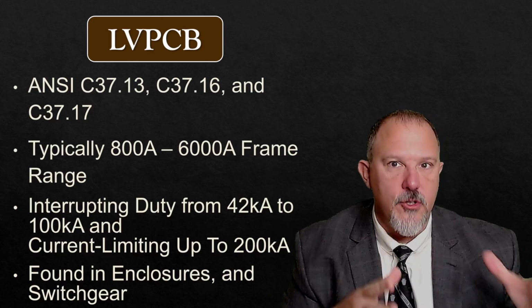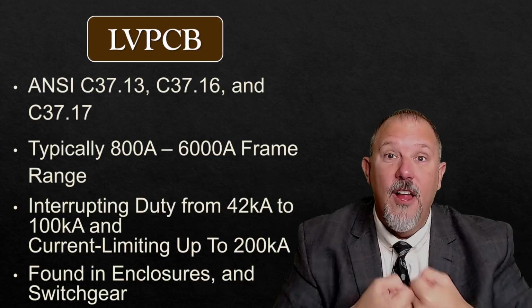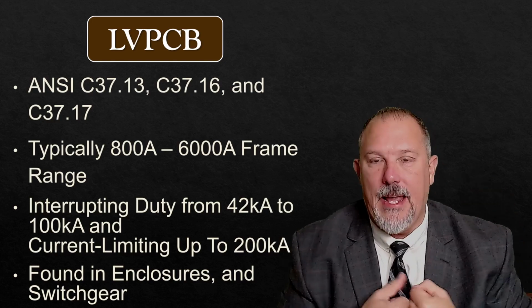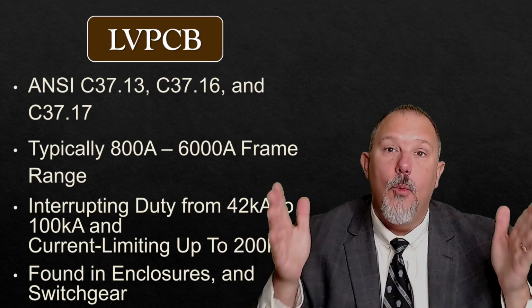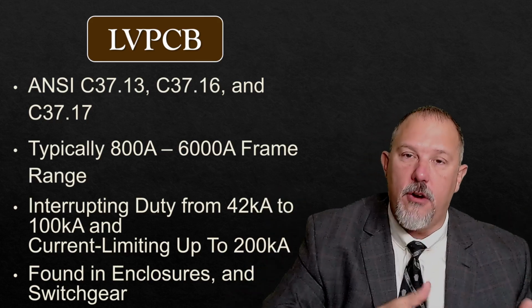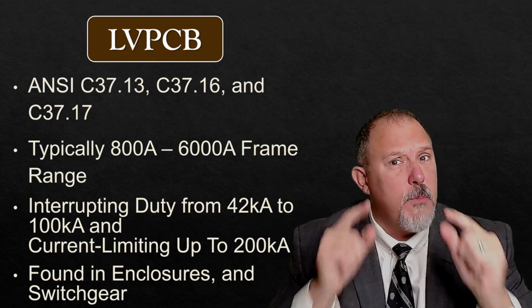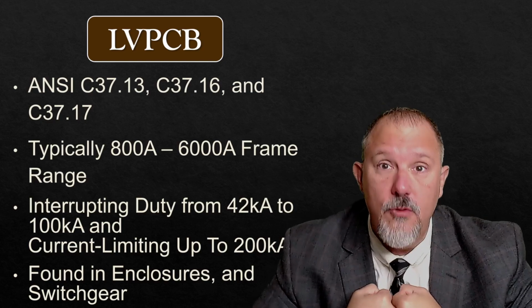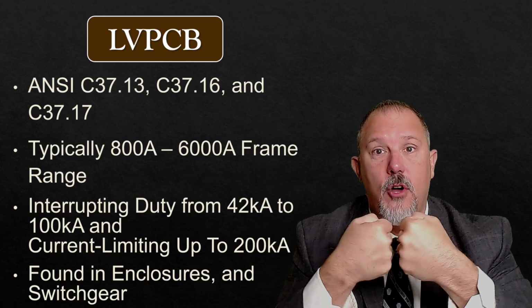Insulated case circuit breakers are smaller. They're not going to be able to hold those contacts closed for up to a half of a second as high as this beast can. It's going to go into its instantaneous region without an intentional delay at lower current values because it just can't hold those contacts closed. Remember, the hardest part for a circuit breaker is to keep the contacts closed. And what you want to not have is chatter on those contacts.